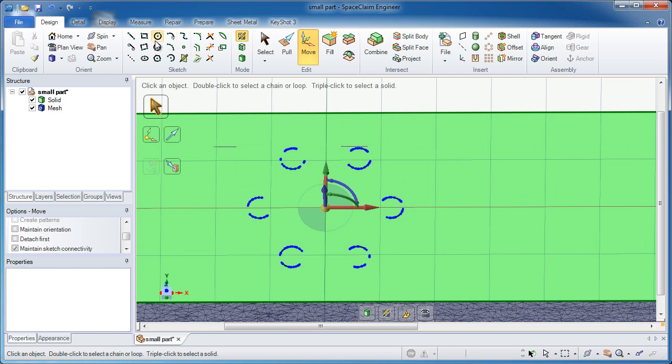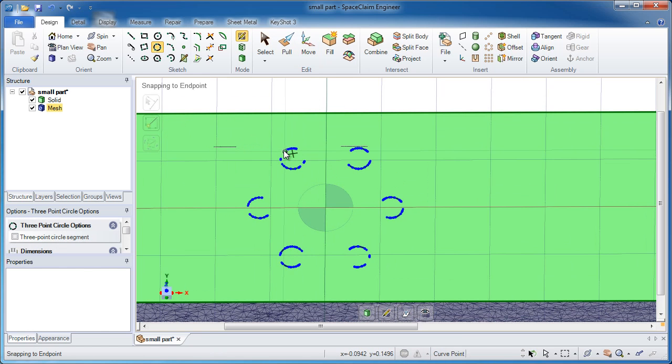So it's simple. It just means I need to take an extra step in the way of recreating some 3-point circles. Now I'm going to do every other one. Instead of drawing all 6 of them here, I just need to do every other one, and in doing so I will have established a center point. If I draw a 3-point circle around the small circles I just made, I've established a center point.